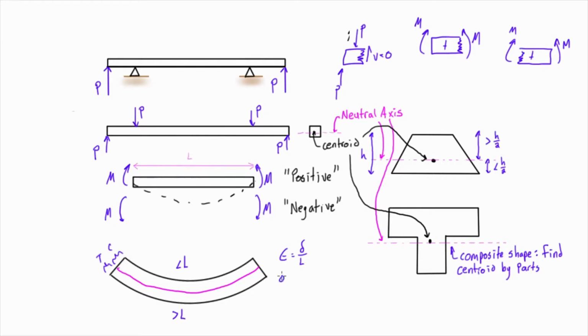So we have Hooke's law, which says the normal axial stress is equal to the modulus of elasticity times the strain. If we rearrange that for strain, we get that it's equal to stress over E. And stress, if you remember, is just a measurement of force over area. So we're getting P over AE basically.